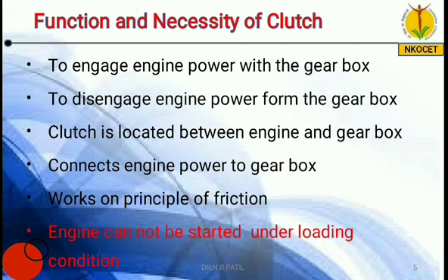Because when you want to run your engine, when you want to crank your engine, it should be free from the load. And how can you make it free from the load? By means of clutch. When you operate the clutch, the engine is cut from the rest of the system, and thus it is very easy to crank or start the engine. So this is the reason why we need clutch.